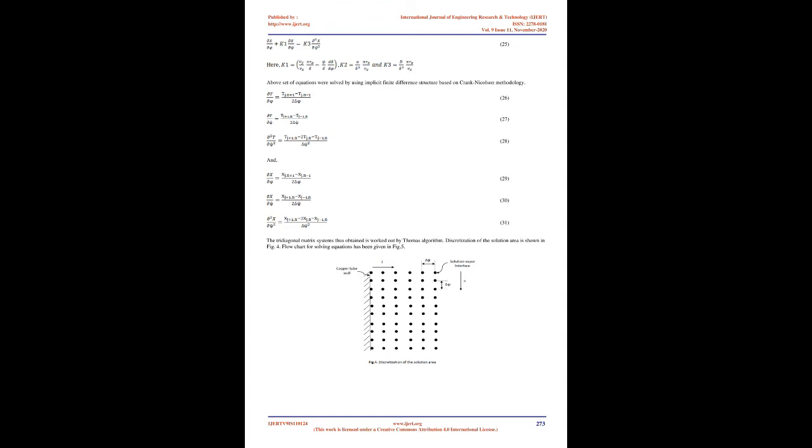Energy released at the solution-vapor interface due to absorption of vapor is equal to the product of absorbed mass flux and heat of absorption. Balancing the heat transfer, the following relation is established, Equation 14. Heat transferred between vapor and falling film is negligible. Thermodynamic equilibrium exists at the vapor-solution interface. The following equilibrium condition at the interface is given in Equation 15.